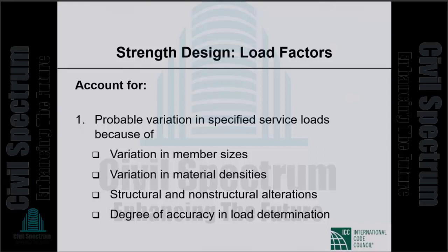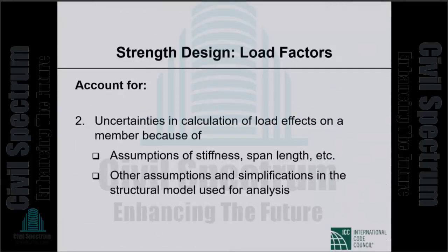Why do we apply load factors? Probable variation in specific service loads because of variation in member sizes, variation in material densities, structural and non-structural alterations, degree of accuracy in load determination. Also, uncertainties in calculation of load effects on a member. So we go from load to load effects by analysis.